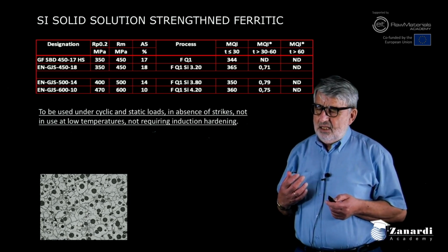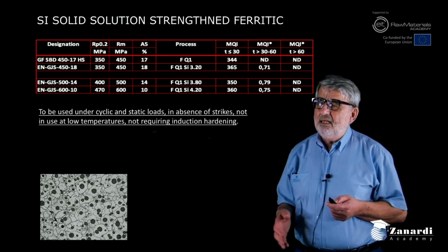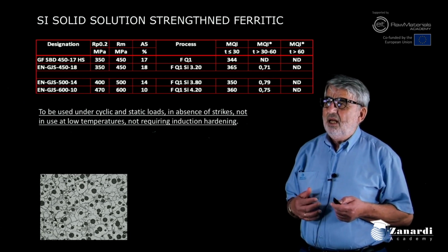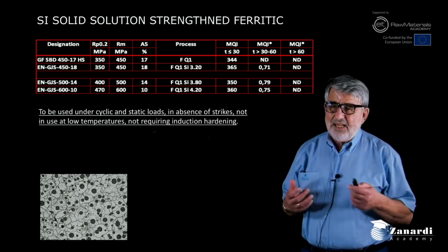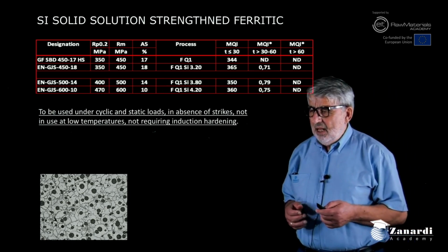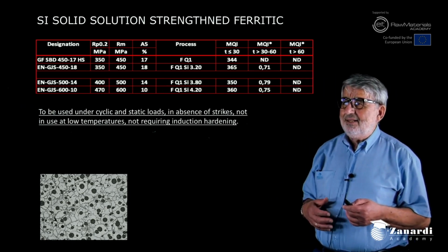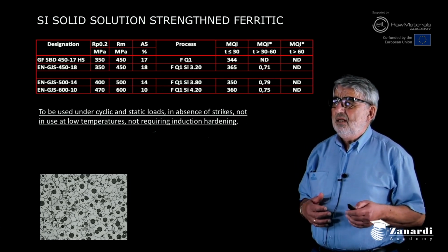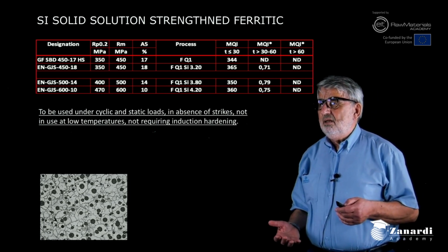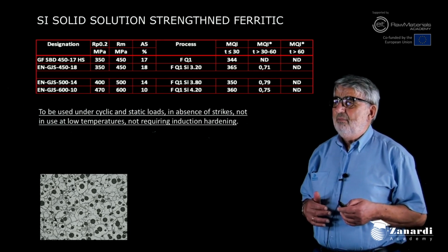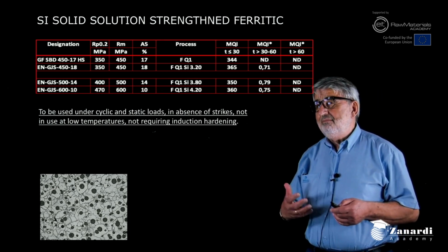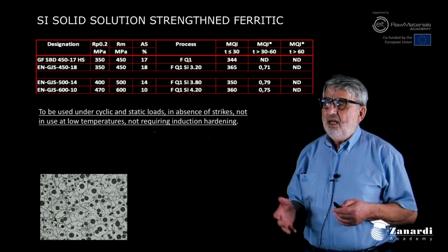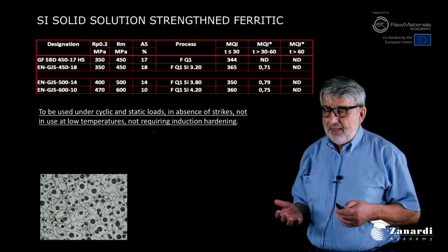and it happened that starting from practical foundry needs of recycling the returns, in the 90s some high silicon grades of 3.4–3.5% were developed, which traditionally was believed to be brittle.